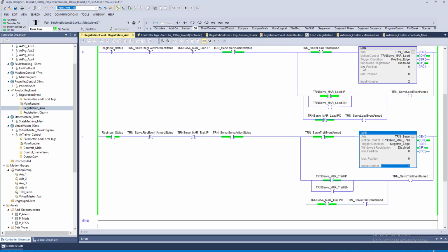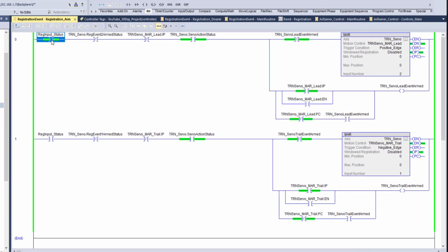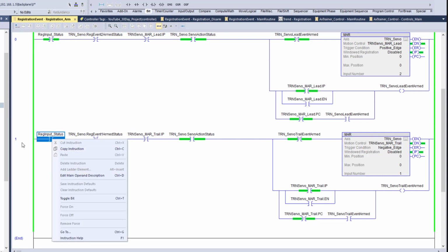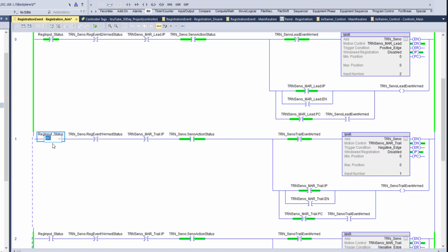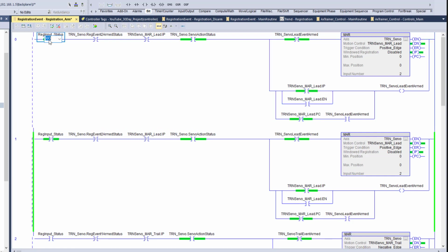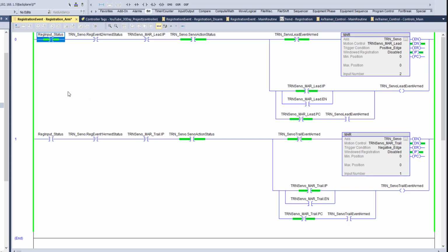Now, why am I using the negative side, basically an XIO up here and an XIC right here? I'm using XIC here, and right here I'm using XIO. Why am I doing that? I'll explain this to you: it's because I'm also using the arm of each one of these. If I were to choose to use the arm of this one, one of these instructions would error out.